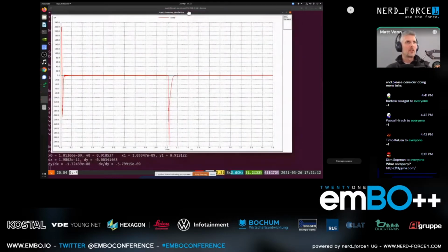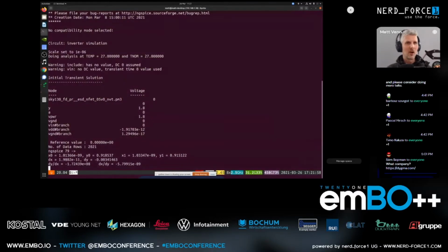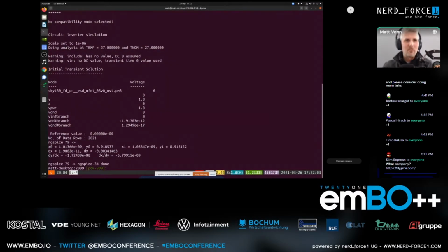And then here, so I've done like, I don't know, 10, 15 years of firmware and microcontrollers, and a lot of stuff I do needs low power. And I kind of understood, yeah, okay, saving power, you've got to do this, got to do that. But I never really realized that CMOS gates use this current when they're switching, only when they're switching, until I started looking into this. And this really opened my mind to this, and it helped me understand why clock gating is used to save power with embedded stuff. You turn off a clock to a whole section of logic and it uses less power because the CMOS is only using power when it switches, and that's its great advantage over NMOS. So that was something new that I learned that might be interesting to the embedded crowd.